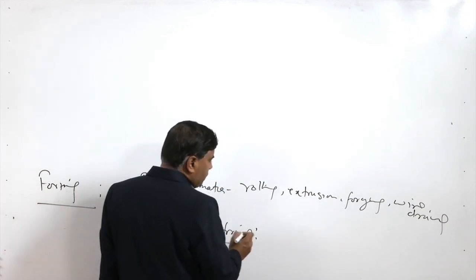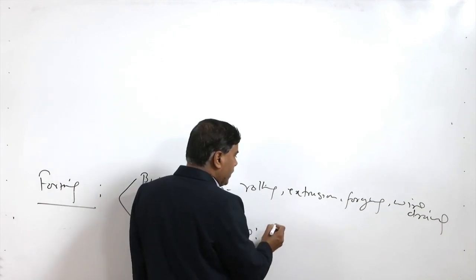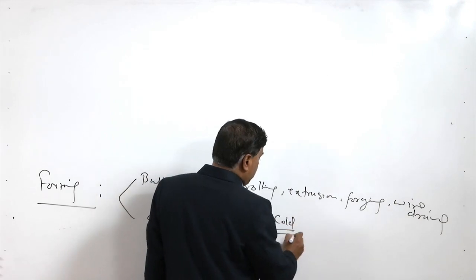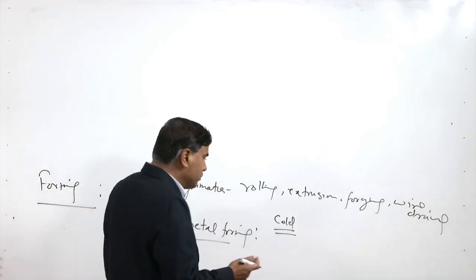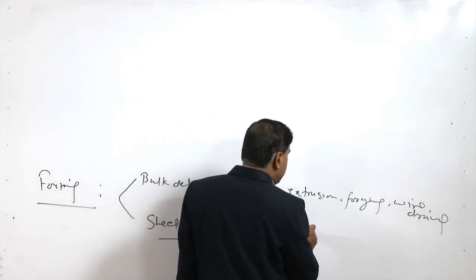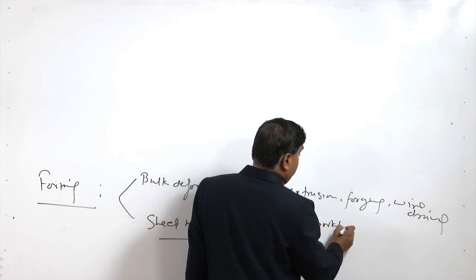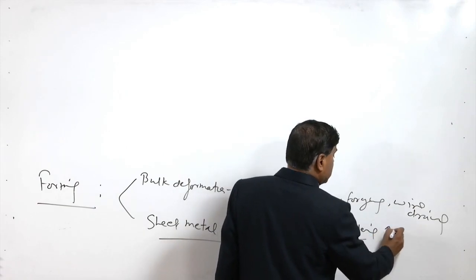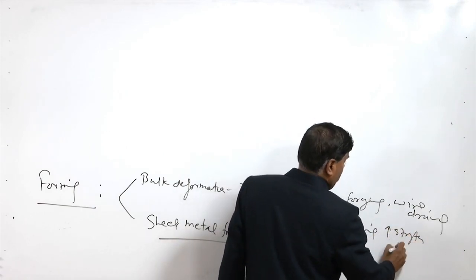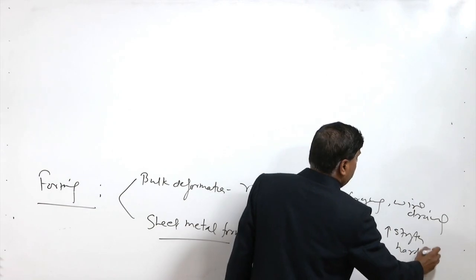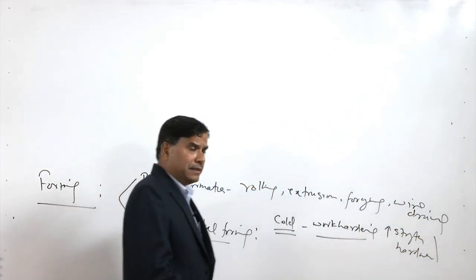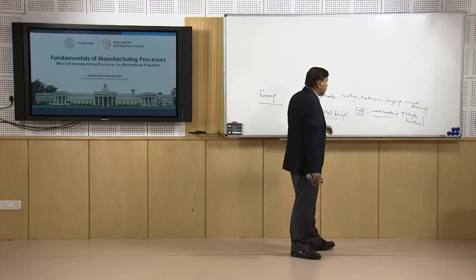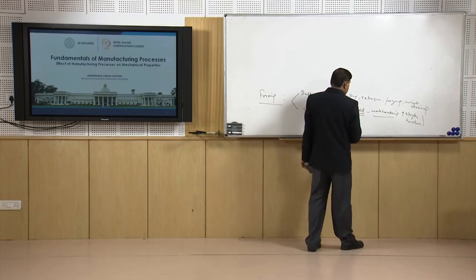So, in these processes where deformation is involved, if it occurs at low temperature, like in cold processes carried out at room temperature, the deformation leads to significant work hardening. This work hardening increases the strength and the hardness, however at the cost of the ductility and toughness, but sometimes there is no major drop or compromise with the strength and the toughness.